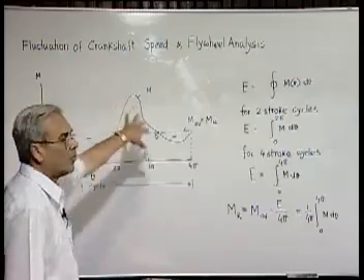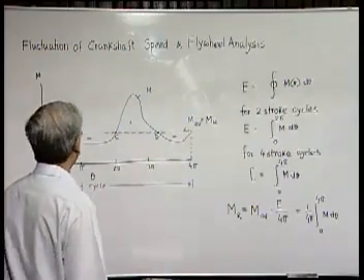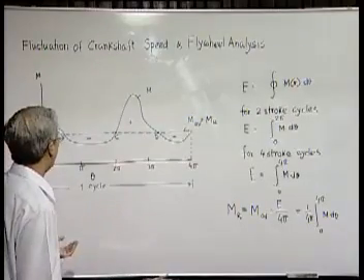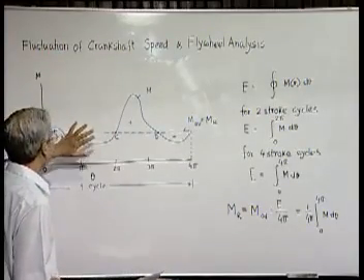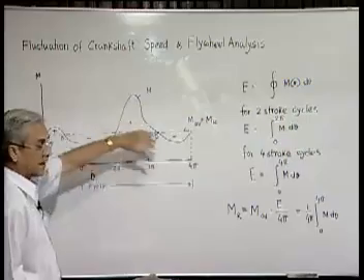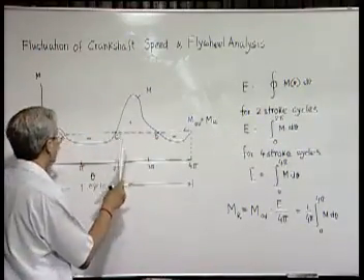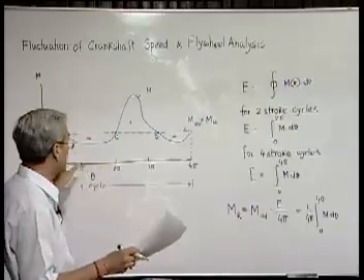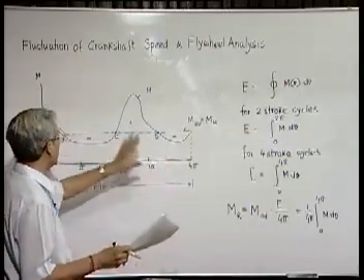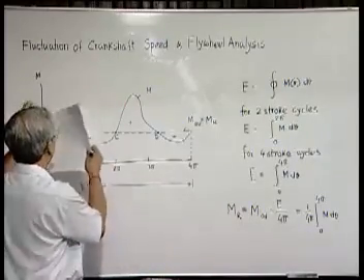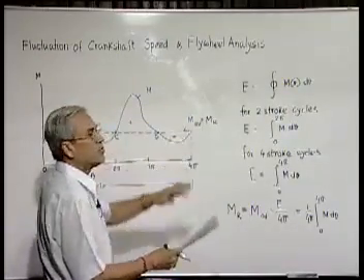It can have many more lobes and be different, because remember, this is a case of a single cylinder engine. If we have more than one cylinder, then what will happen? The turning moment diagram of one cylinder and the turning moment diagram of the other cylinder will have to be superimposed with suitable lag. In case of two engines, obviously they will be separated by 2 pi angle, and so the final turning moment will be a superimposition of the data.